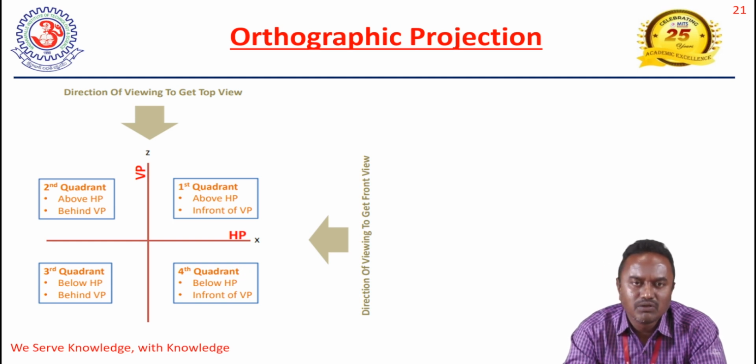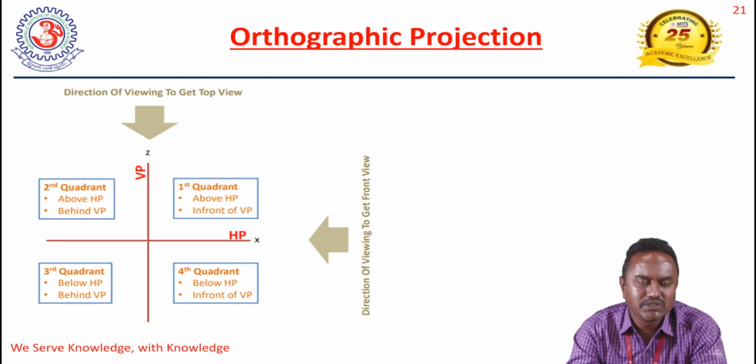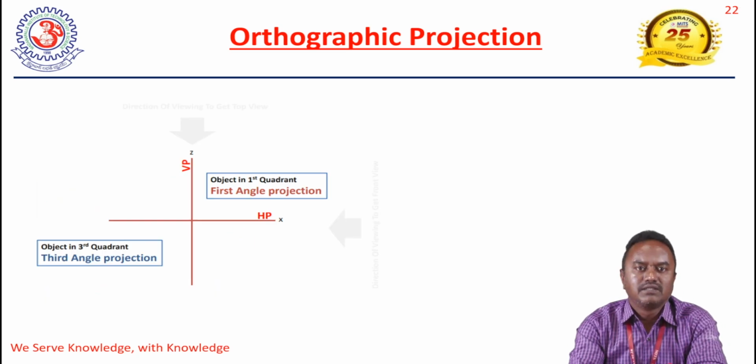So depending on the quadrant, we can say the projection. If any component is placed in the first quadrant, that is called the first angle projection. Second quadrant means second angle projection. Third angle projection. Fourth angle projection. So normally we use first angle projection and the third angle projection in many drawings. So first angle and the third angle are very important.